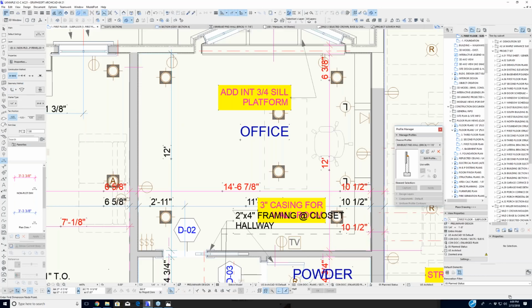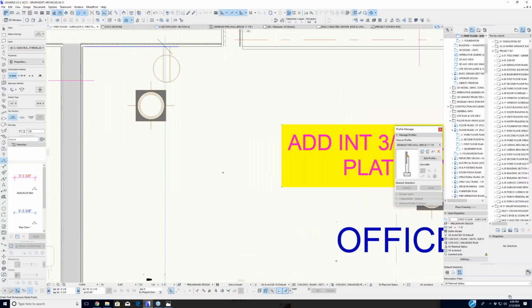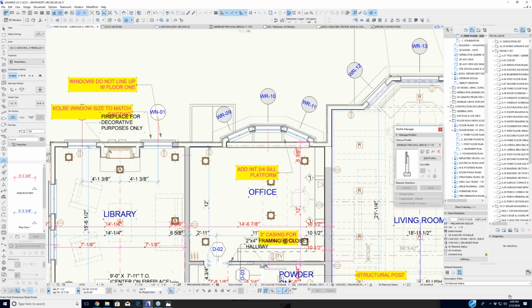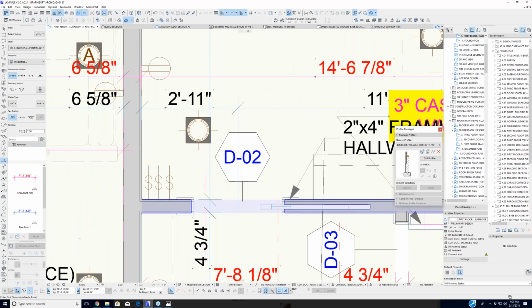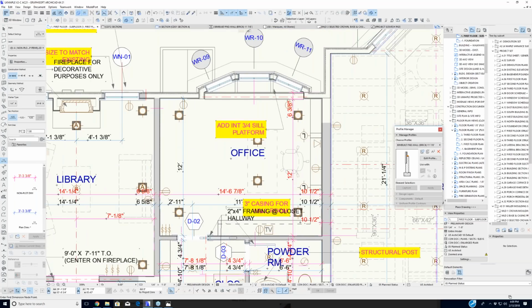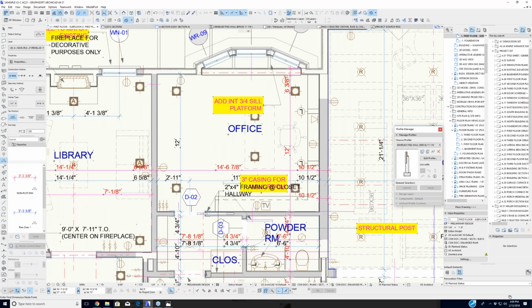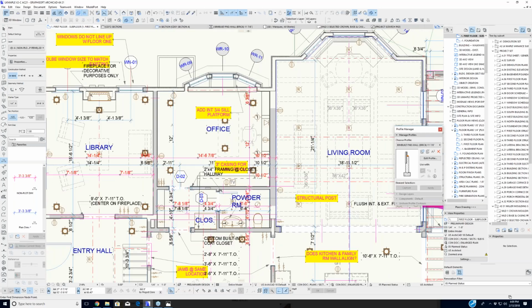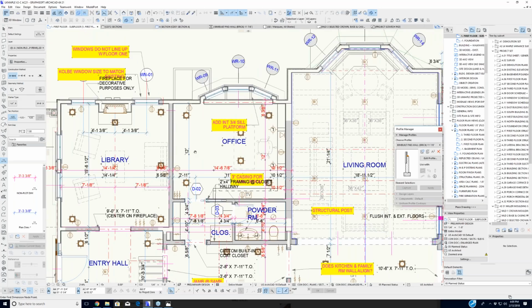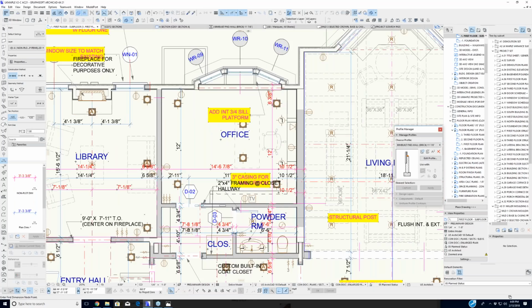So that was saying, I'm not giving them a core. I'm giving you my end goal. I want that to be a finished 12 feet. And then they'll accordingly set that stud up, knowing they're going to build this up with 5/8 and they're going to build that up with 5/8. A lot of times it's easier doing that, because when you start going core to core or measuring the core and you're using 5/8 sheetrock, you're immediately throwing somebody into fractions of an inch. It's going to show 12'3 and 2/8, and it's harder to add on the fly in the field than it is just showing finish. Okay.